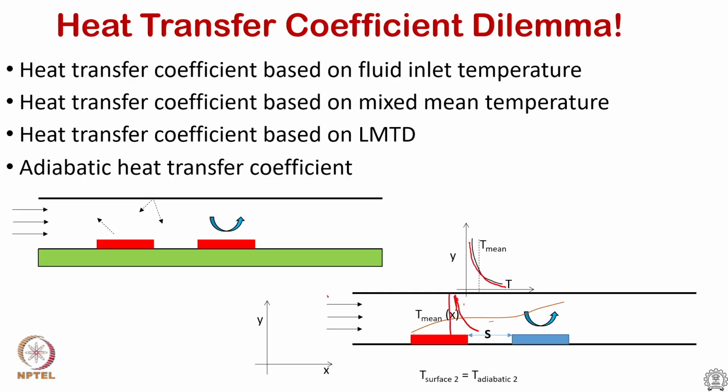So this will be T inlet. Here it is going to be T inlet, because my boundary layer has grown only till this point, anything above this is going to be flat. T inlet temperature, and it starts to be higher as we go, as it is in contact with this hot wall. So you have a temperature profile that is different throughout the height of the duct.